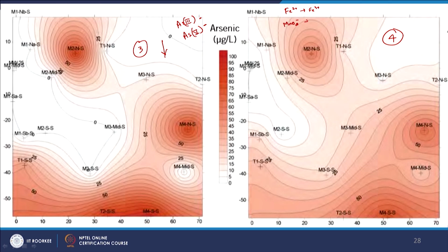and then we had Fe2 plus going to Fe3 plus with release of the relevant electrons, and MnO4 minus going to MnO2, the solid. Both these solids, the Fe3 plus one that precipitates out and MnO2, while they are precipitating out, can act as sites for adsorption of the relevant arsenic, and that is one very probable way, and that is typically used out there too, to remove arsenic. This is one probable way how arsenic concentration would have decreased. The planners might not have planned for it, but that is one unintended benefit.